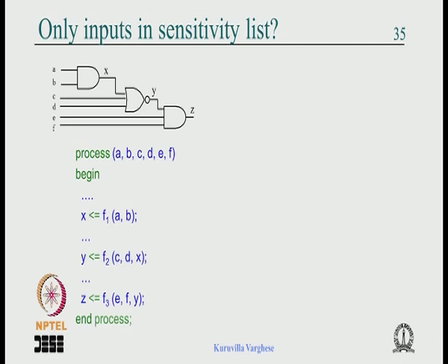Now a very quick recap. We have seen how event driven simulation, event driven computation resolves the concurrency. In the case of no delay, we add a conceptual very small delay, delta delay, which keeps track of the sequence of computation, and if there is a feedback, there is no issue. Depending on the events the computation continues. Two cases: it oscillates or it becomes stable.